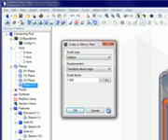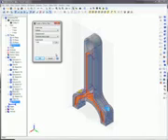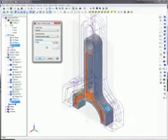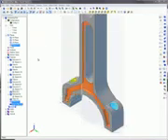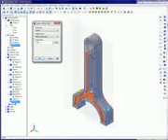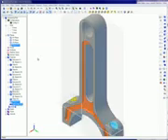Here is a run-through of the scale or mirror part options. A scale of 1.5 will be used for each demonstration. The preview geometry will give you a good idea of what the result will be before the OK button is clicked on. The scale types are uniform, which scales features the same in the X, Y, and Z directions, shown here with the transformation point occurring at the origin, X0, Y0, and Z0. This is another uniform scale, but this time the transformation will execute at the part center point.